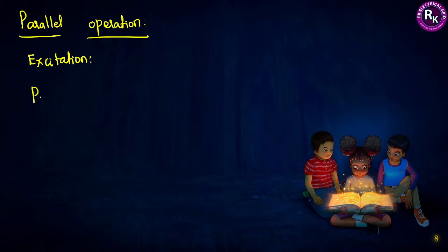The second one is the prime mover. Now, always keep in mind that by changing the excitation or by changing the prime mover, we can change the reactive power and real power delivery of the machine. Let us see one by one.